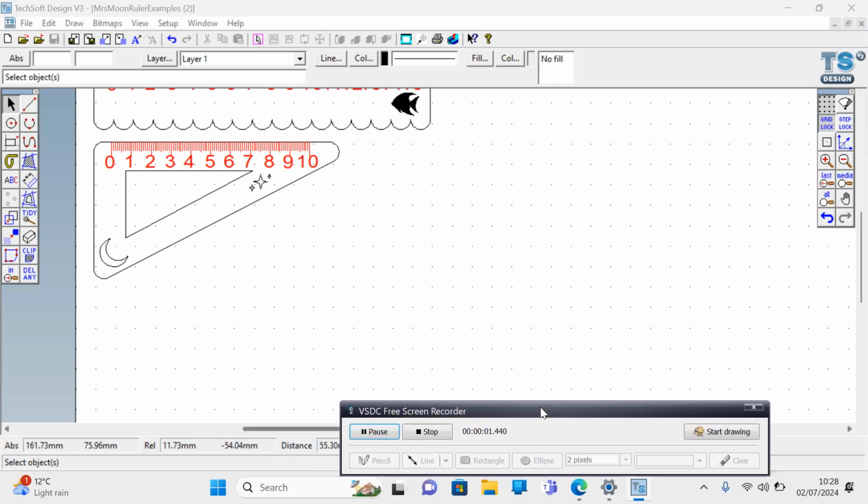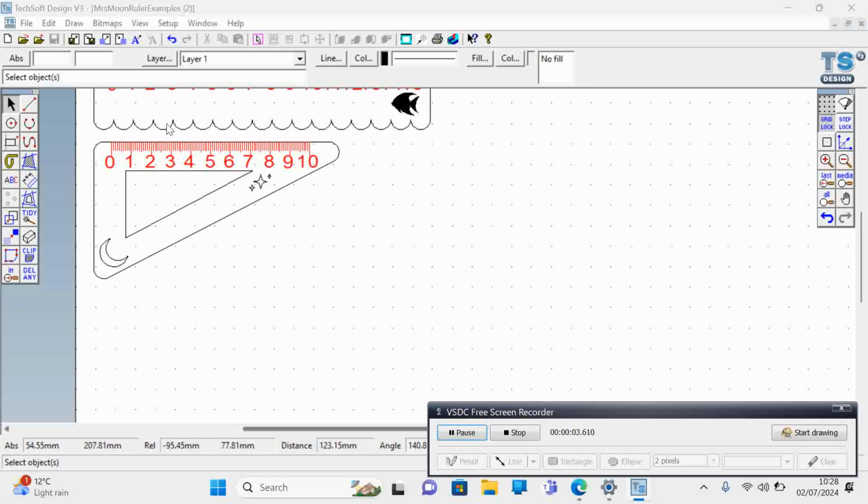Make our set square, like this example here. What you need to do first is make sure you've snapped to grid lock, so that button should be dark grey here, and you're going to want to use the line tool. Okay, this line tool up here.